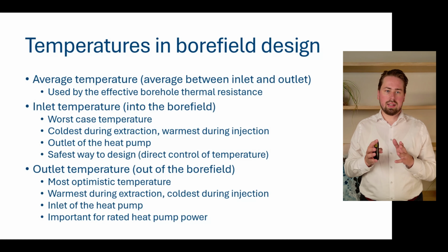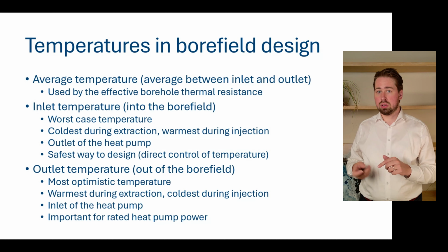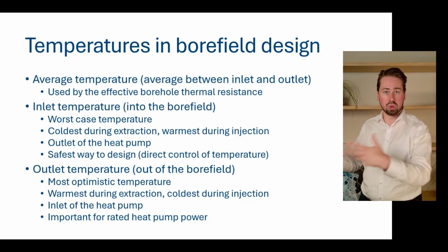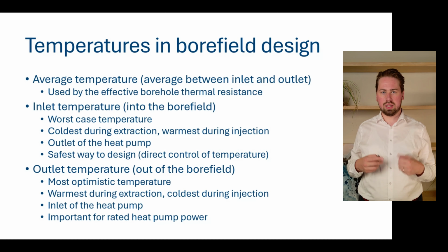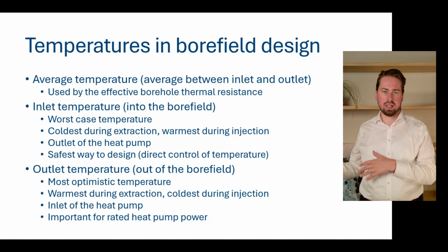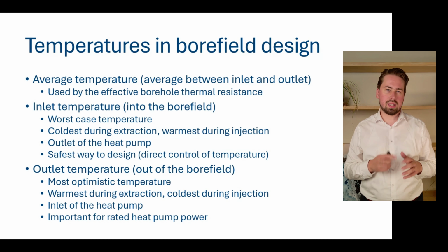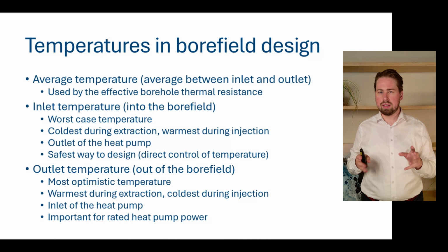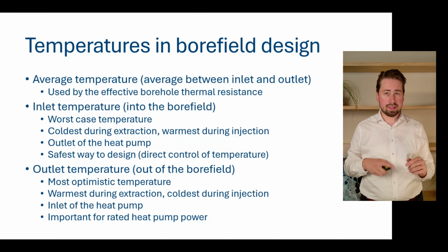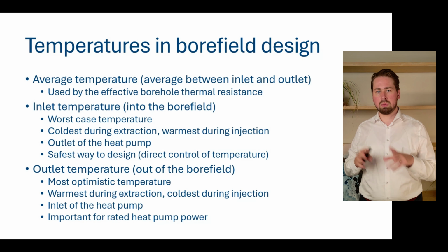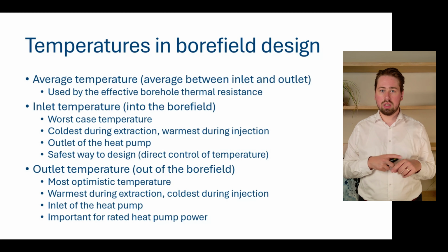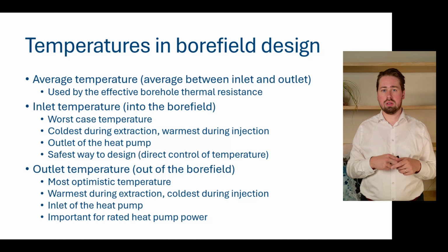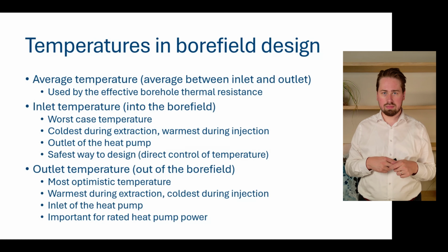But again, if you design for the inlet temperature with the same threshold, since the inlet temperature is always a little bit worse than the outlet temperature, colder or warmer depending on extraction or injection, you're always safe on that side as well. So this was a little bit theoretical. Let's jump into GHEtool Cloud and show you real quick how you can switch between average, inlet and outlet temperature, and how that influences your temperature profiles as well as your required total borehole length.